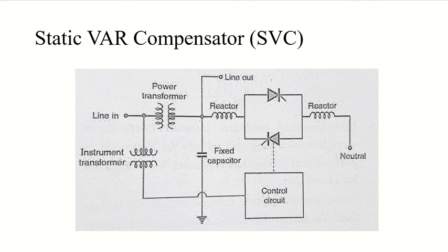It is negative if the reactance is capacitive, and positive if the reactance is inductive. By doing that, it regulates your voltage, improves the stability, provides you controlled voltages, and also prevents over voltages. It also reduces voltage flicker, the flicker which takes place when you suddenly connect a heavy load to your system.